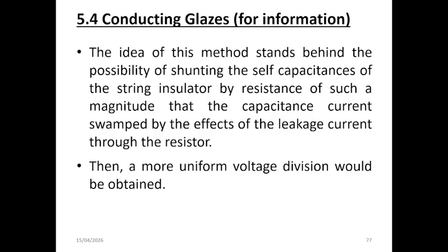So another point is that although this method is mainly of informational interest and not as widely used as other methods, it demonstrates an important principle of controlling electric field distribution through resistive means, and we will use this principle to reduce the impact of the shunt capacitance in insulators.